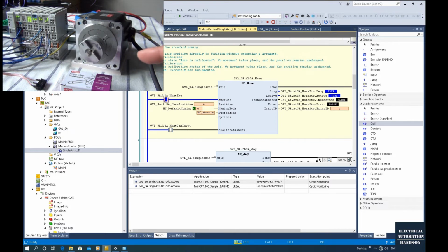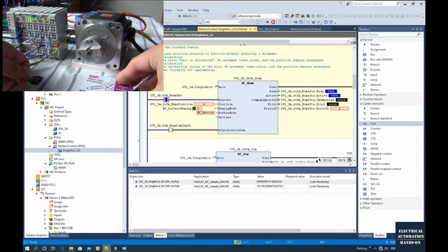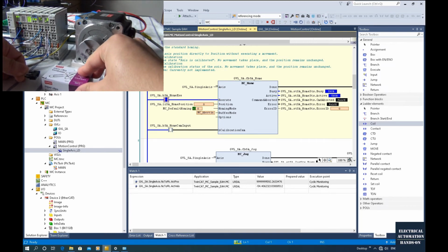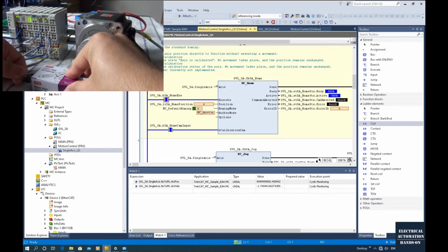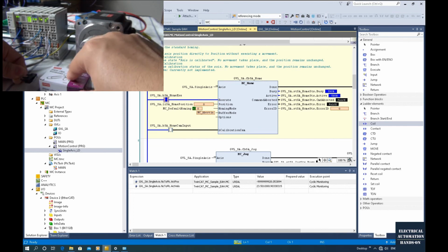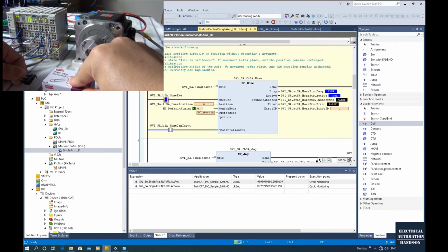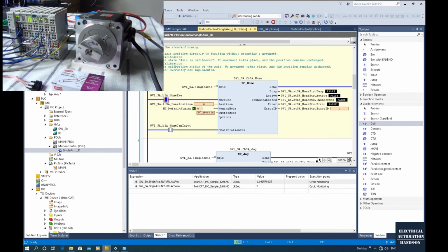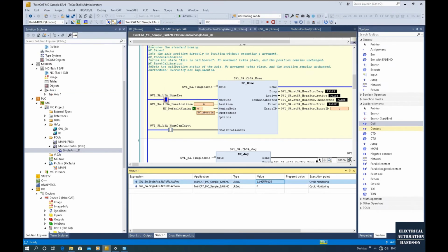So now this step motor is traveling back. That means this box is traveling backward towards the home sensor. And once it touches this home sensor, the step motor will travel back. You can see it travels in the positive direction and leaves this home sensor. After it leaves this home sensor, it's still moving. That means the motion is searching for the zero mark from the incremental encoder. Okay, once it gets here, my incremental encoder zero mark is around here. Once it gets here, it stops. You can see it stops itself. This is that process. Okay, let's do it again.